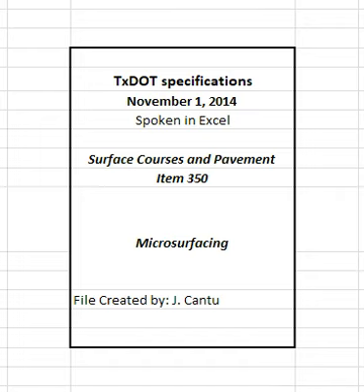2.6 Tack coat. Furnish CSS1H or SS1H for tack coat binder in accordance with Item 300, asphalts, oils, and emulsions. Specialized or preferred tack coat materials may be allowed or required when shown on the plans. Do not dilute emulsified asphalts at the terminal, in the field, or at any other location before use. 3. Equipment. Maintain equipment in good repair and operating condition.